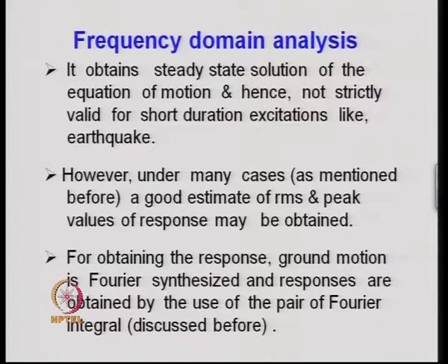Frequency domain analysis in fact provides a steady state solution for the structure. It cannot take care of the transient phenomena, that is the transient part of the response that comes before because of the initial state of the system.